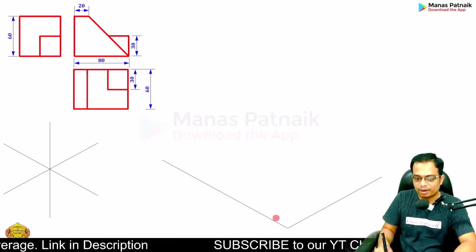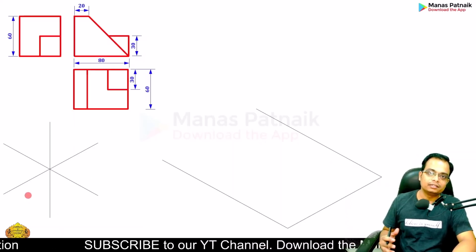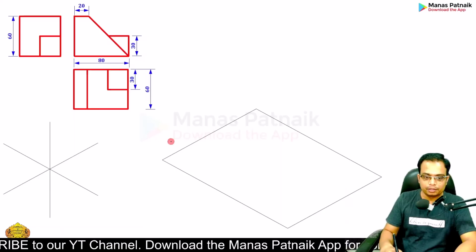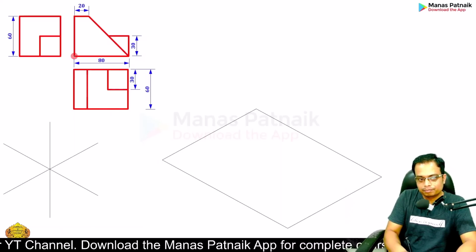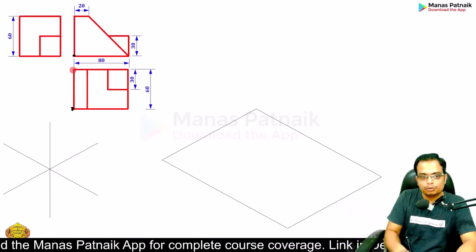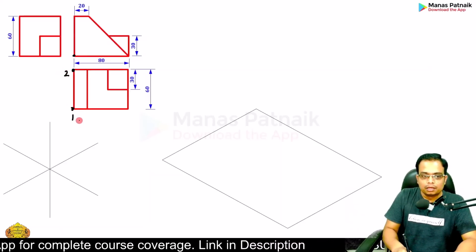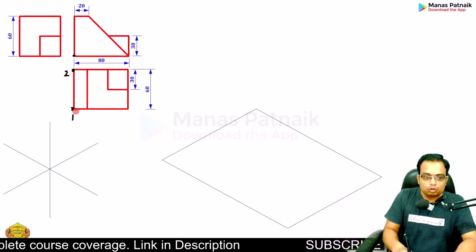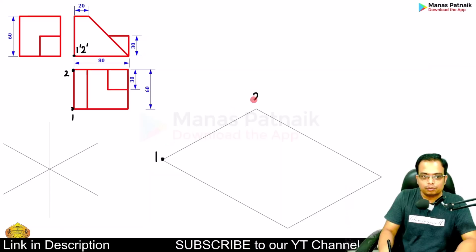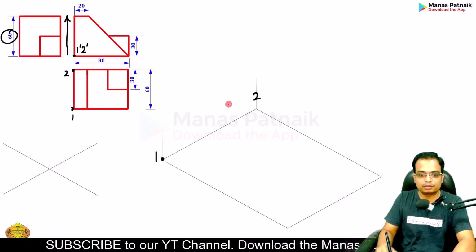Then what you need to do is move parallel here. Note these isometric lines are going to help you align your mini drafter. And then connect. Now what should we do now? This by the way is 80. Now, in the top view, right at the base, there are 2 points. Let's say this is 1, this is 2. When you look at these 2 points from the front, they appear over here, 1 dash and 2 dash. So I can write this as 1 and 2. Now these 2 points will be given a height of 60 millimeters. So let me give them some height.